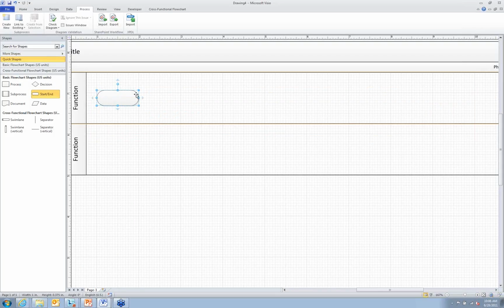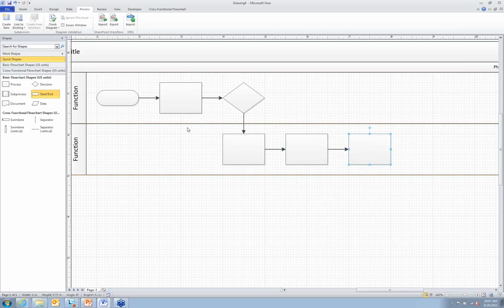If I go ahead and continue, I'll use this feature called the Quick Shapes Mini Toolbar. I highlight to the right of the shape, and it automatically gives me the most likely next shapes I'm going to use for this diagram. So pretty quickly, I can go across and down through the swim lanes here and get that basic whiteboard diagram, that basic process diagram, created. In some cases there's going to be other elements, so I can use the Quick Shapes Mini Toolbar to connect to a shape that wasn't one of the most prominent ones. It's just a simple progression across the page.